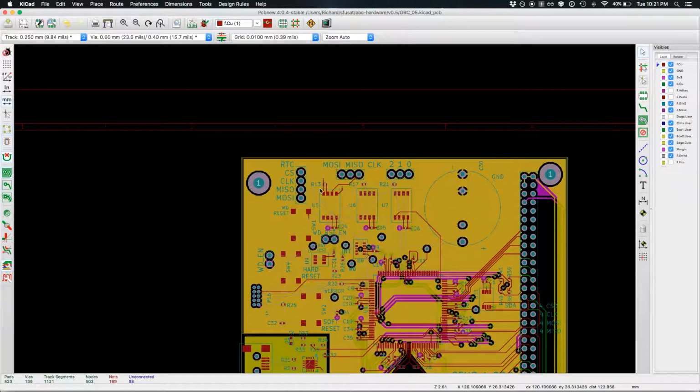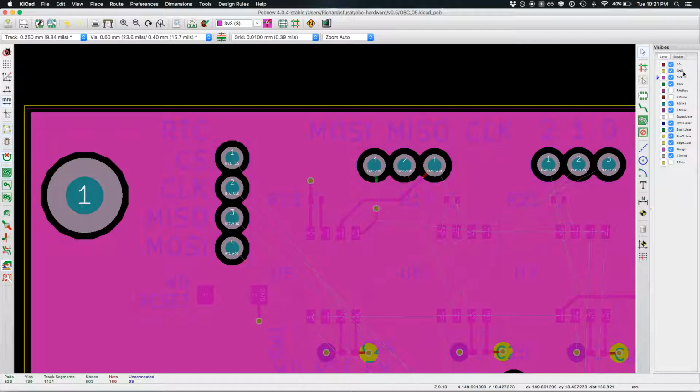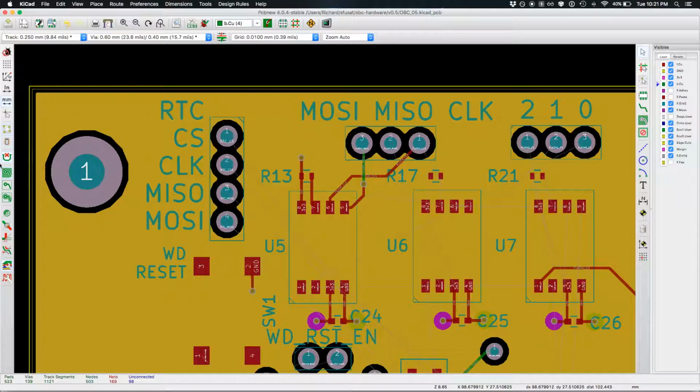And yeah, main recap. Layer 1 and layer 4 are used for routing. Drop vias down for 3.3 volt and ground. Don't go into layers 2 and 3 for signals, only do the vias into them for your power and ground connections.